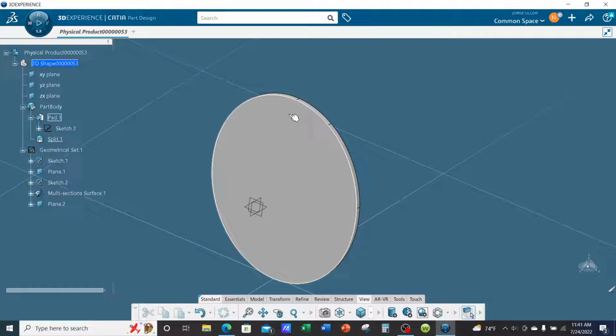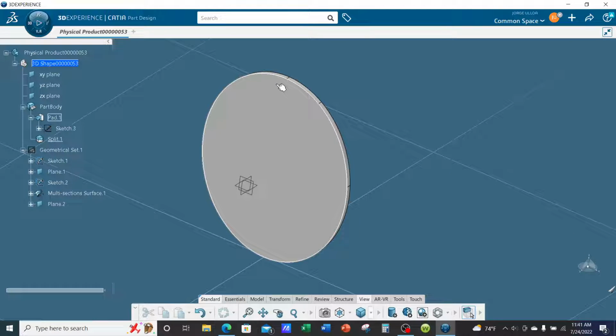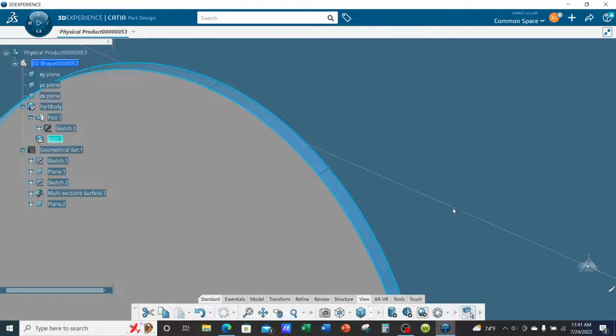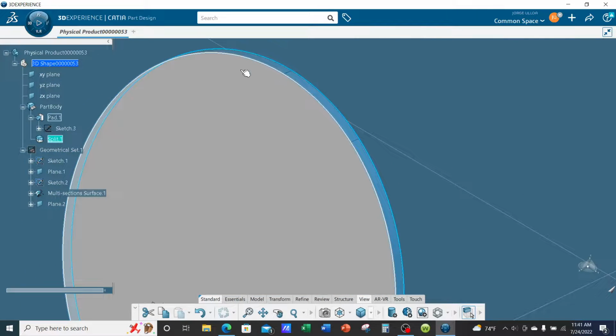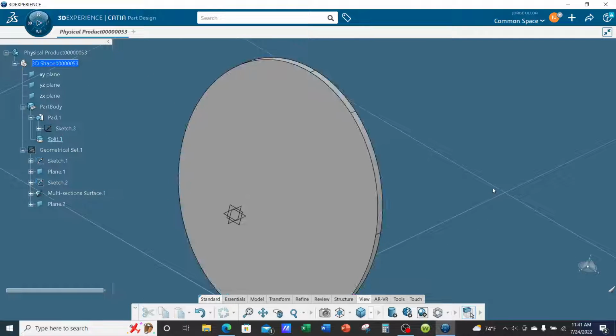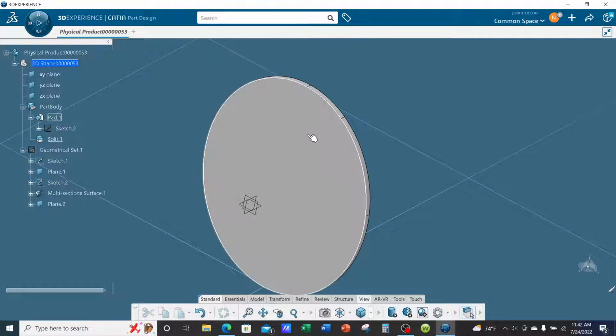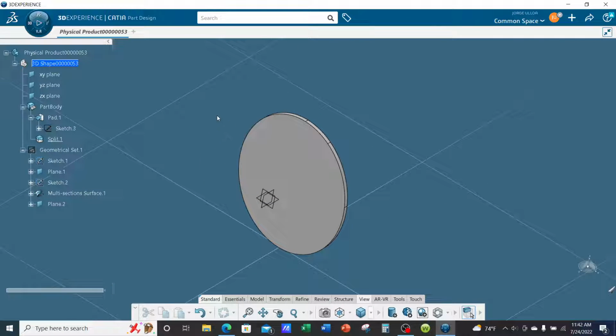All right, so let's say we're going to machine off and keep maybe a 1/2 inch thickness on this frame on the inside, and we'll leave the flange at 2 inches, but we're going to remove the inside so it has a thickness of only 1/2 inch. But before I do, I'm going to also create an opening. So let's go ahead and create another surface on the inside.